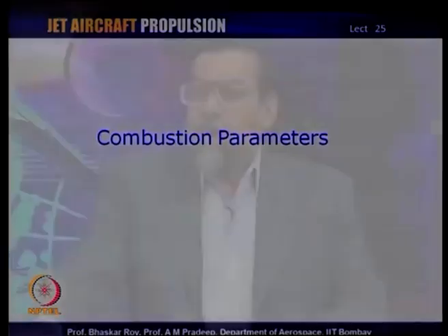Now, the first parameter we may like to look at is pressure loss. You see, when the flow comes from the compressor, it has been adequately compressed, and the amount of compression it has gone through has been decided by the engine designer as per cycle design. This compression that has already taken place is vitally important for the efficiency and good performance of the engine. Now, during the process of combustion, there is every possibility that some of this pressure would actually be lost.